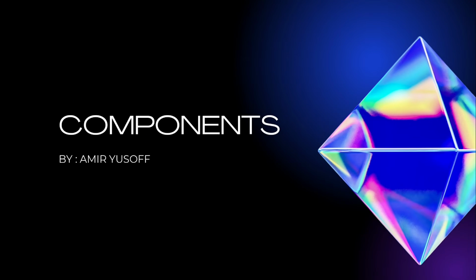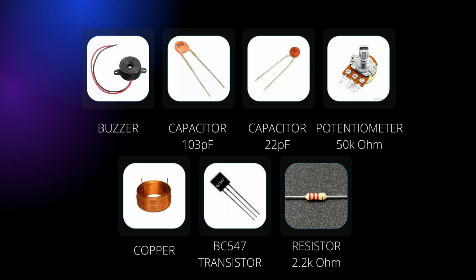So for the next part, which is about the components involved in this project, there are only about 9 components. The components are the speaker or buzzer, 2 capacitors of 103 picofarad, 1 capacitor of 22 picofarad, 1 potentiometer of 50 kilo ohm, 2 NPN type transistors that are BC547, 1 resistor of 2.2 kilo ohm, a power supply of about 9 volt, and the last important thing, copper wire as the inductor in the circuit, which we make into 2 sets of 20 turns of copper wire in this project.